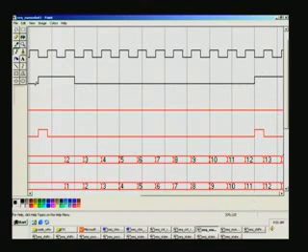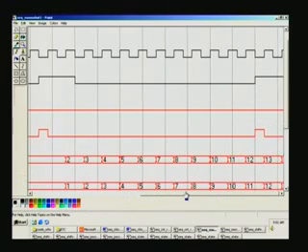You have applied the first trigger, it started working, and while it is working, if you wantonly trigger it, it won't trigger. It simply ignores any number of such trigger inputs. Although that rising edge of run delay is still encountered, it will be ignored because the counter is already servicing the previous trigger as such.